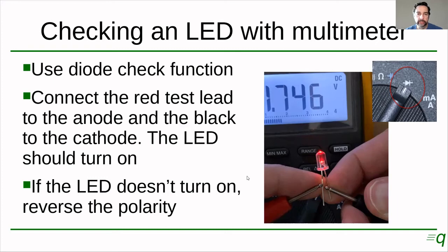So again, if the LED doesn't turn on, just reverse the polarity. It may be that that particular LED or manufacturer or that particular model has the longer terminal as the cathode, but it is unlikely. I don't remember ever seeing one of those.